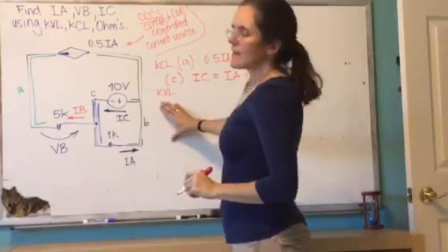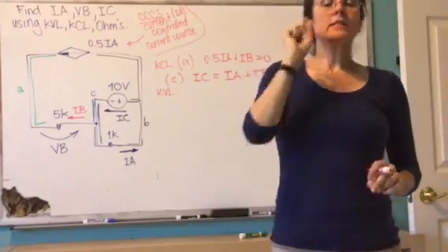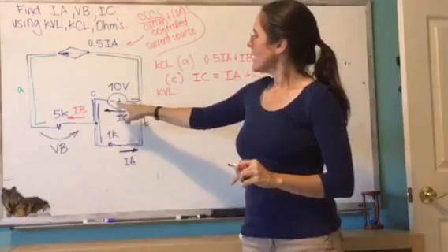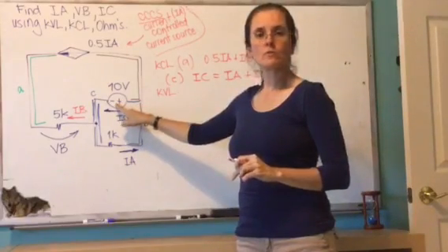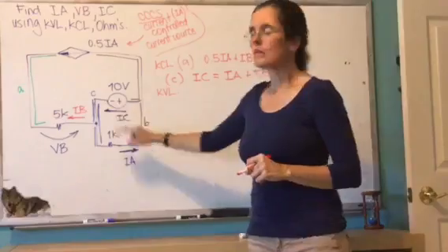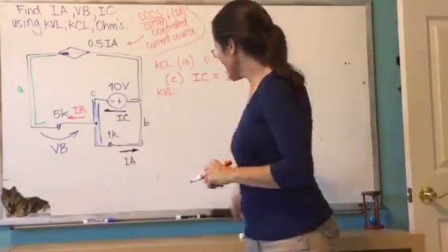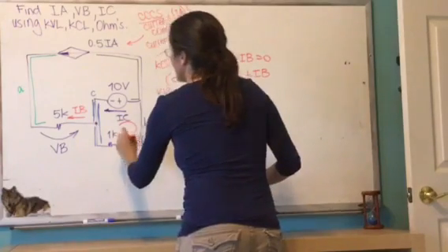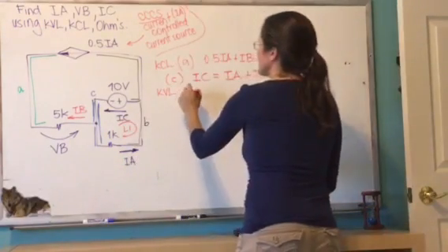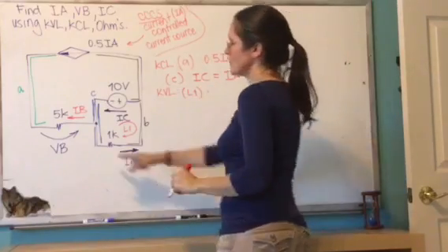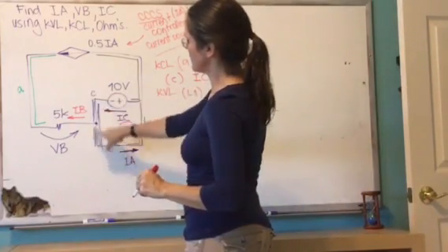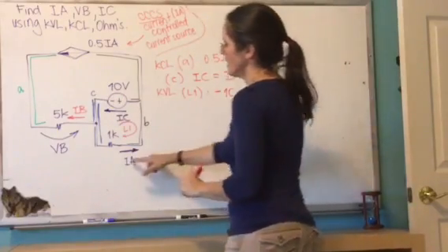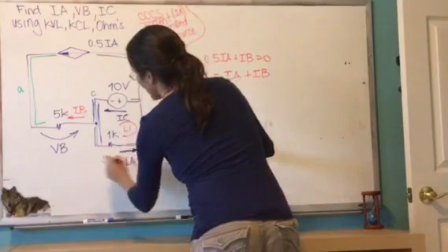And now I'm going to write KVL for what matters. In this case, the main KVL that I can write has to involve this 10 volts loop, the loop that has a 10 volts. And basically, the simplest is this loop here. So I'm going to call this loop 1. I'm going to write KVL for loop 1, and I'm going to start here on this node C, and I find the 10 volts, but I also find the minus. So it's minus 10.